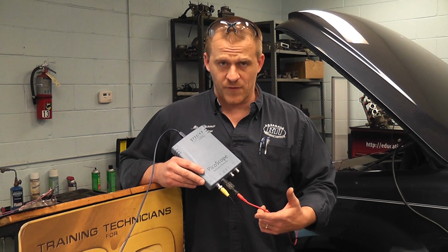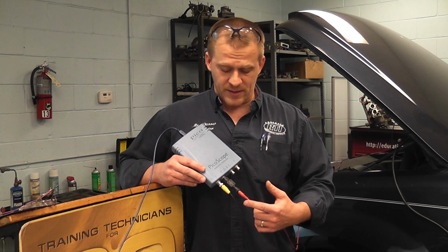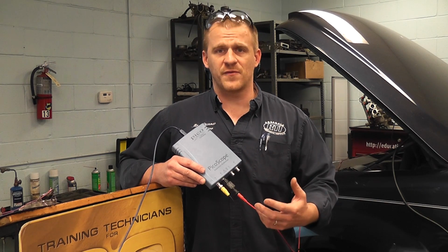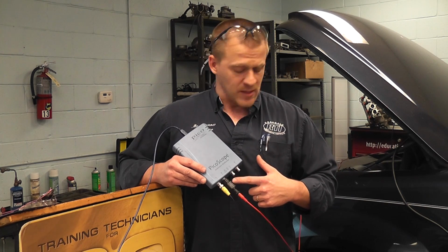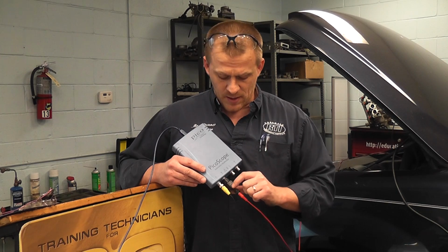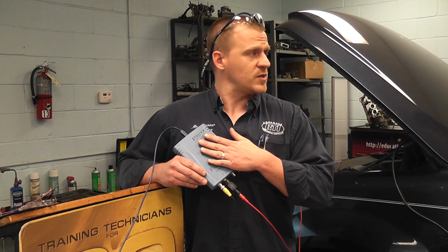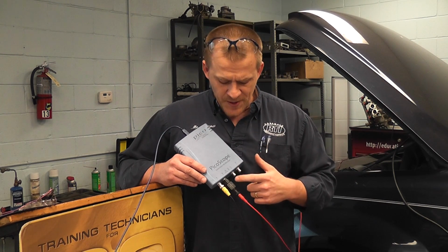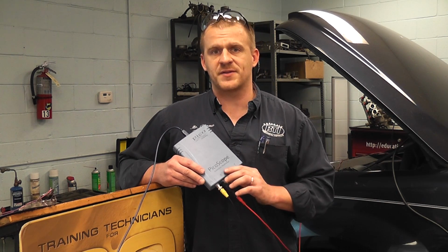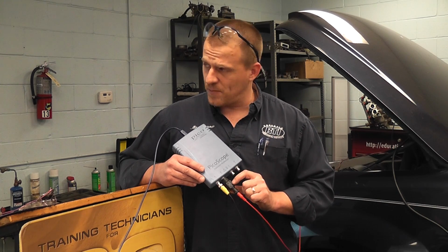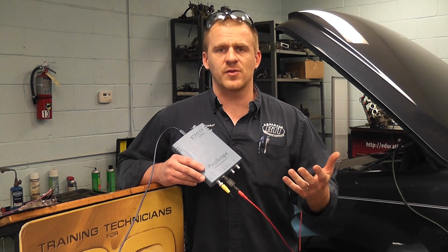Now, one of the things you have to be careful of when you're looking at anything that has a collapsing magnetic field is very high voltage spikes. It's not uncommon to see upwards of 400 volts on a primary voltage waveform. So I've put an attenuator in here, a step down by 20 in voltage, and that's going to protect my scope. This scope has a maximum of 100 volts on this model, the 4000 series. This steps it down by 20 so I can safely read much higher voltage without damaging my scope. I just have to tell my scope in the settings that I have it in there so I have the right readings on the board.